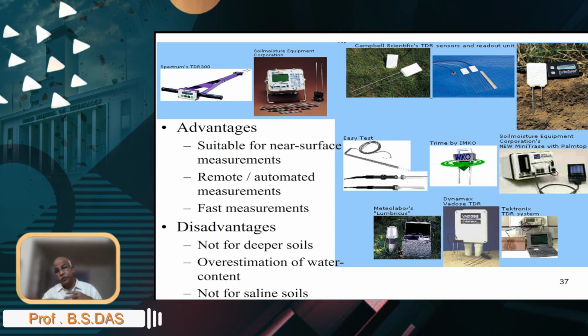So typically around 2 to 3 centimeter sampling volume, and all you need to do is insert a probe. So you should be able to measure every 3 centimeters from the soil surface, so you could almost do a near surface soil wetness measurement using this technology, the TDR, or time domain reflectometry. The measurements are very fast. The whole process takes on the order of about 50 milliseconds.